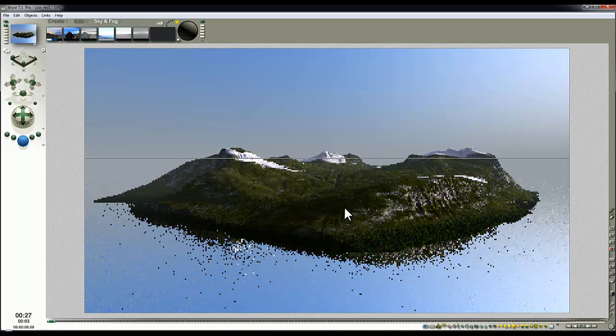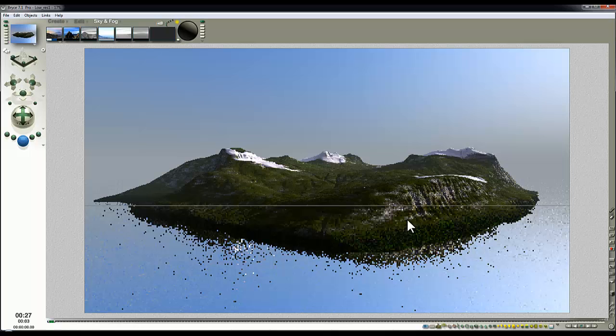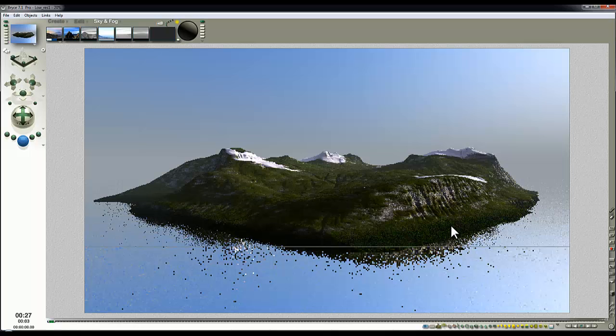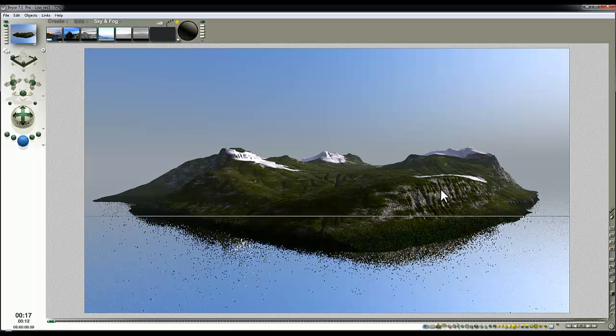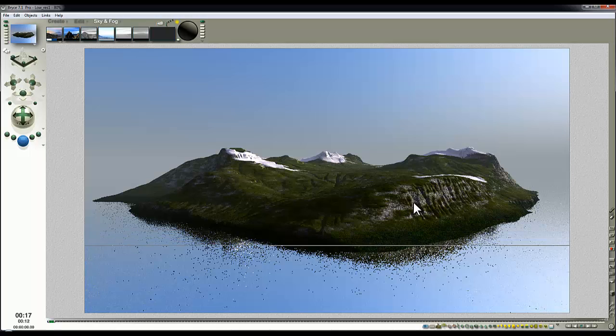Okay, so that doesn't look bad, but the texture's only responding to the altitudes, and in this case a slope, so as the slope gets steeper then it brings in a bit of a rock texture, and this tree texture just coming in where it's low down. But what I really want, because I've got this eroded appearance to the land, I want it to be responding to this in and out here in some way, which would be nice, but it isn't. But that can be achieved through curvature filtering, but curvature filtering is limited in two ways.